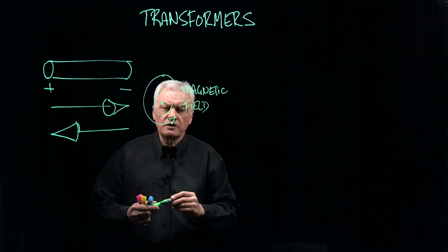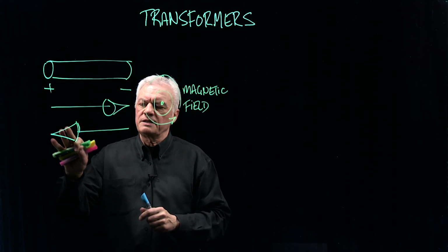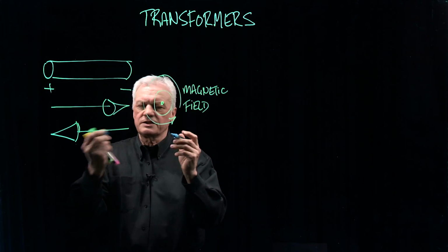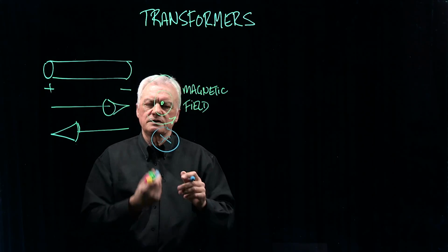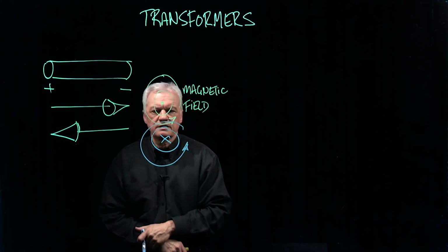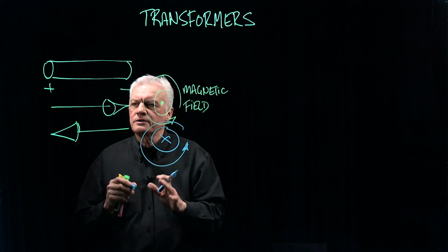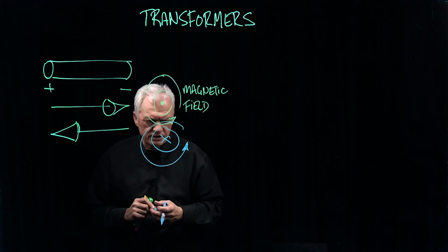Okay. So you're saying, okay, but is that the same for electron flow? Electron flow does the same thing, except what you do is you use your left hand. So if we look at the flow, because it's leaving us, I use my left hand, my thumb pointing away, guess what? My fingers also curl in the same direction of the magnetic field. So the magnetic field, whether it's formed by current flow or electron flow, will still be in the same direction.